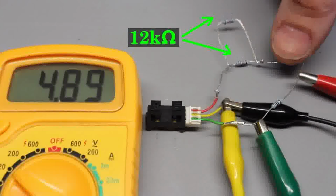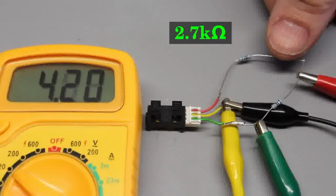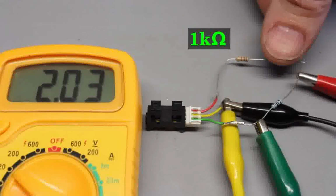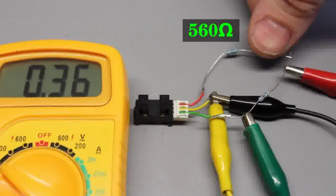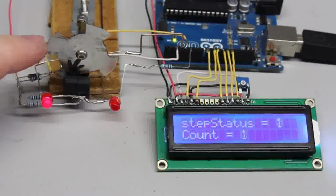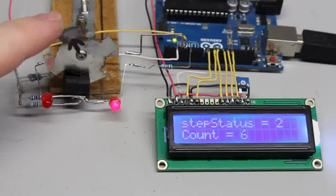Now the phototransistor is connected to plus 5V through a 12 kiloohms resistor, while the resistance value at the LED side is lowered, until we get a reading of less than 0.5V across the receiver. That's a safe configuration for this sensor type at 5V supply voltage. Using two transmissive optical sensors, you can build a rotary encoder as demonstrated in a previous video.